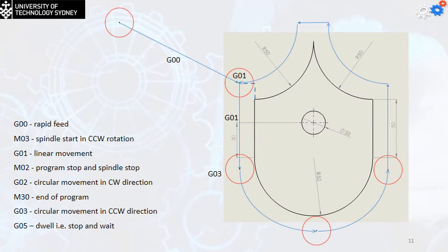It's very simple by using the R code. You don't have to write down the I and J code. So simply it's going to be G03. In this case, we are going to change the x value. It's going to go to the other side. It's going to be something about 100, because we are going to add a radius of 50 plus another radius of 50. We were at -5, it doesn't matter, because what we care about is the end point,